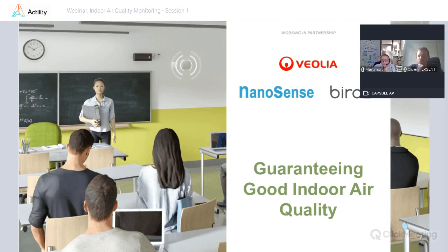Okay. Thanks, Olivier. Several questions for Leonardo. I will bundle them. There is a question on CO2 values, the thresholds that you use, 600, 850, 2000 ppm. Are they based on some kind of official recommendation, or is it your own experience? And are these values related to specific settings, like specific for schools, retail, or offices? And the second question for Leonardo is: is there any display for the CO2 sensors?